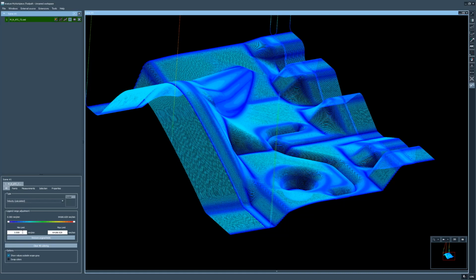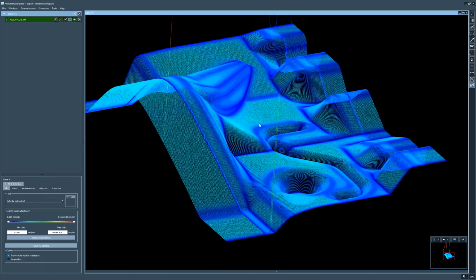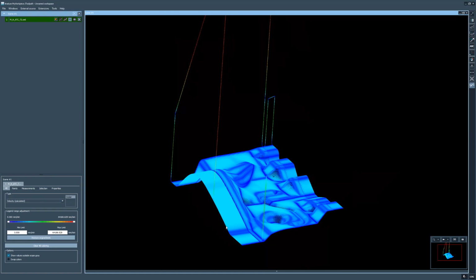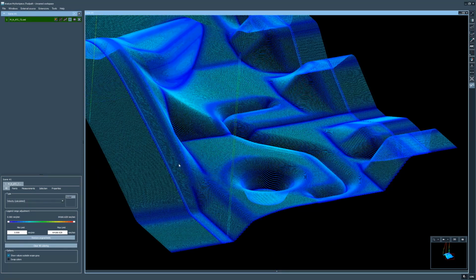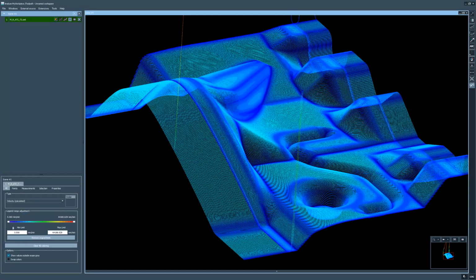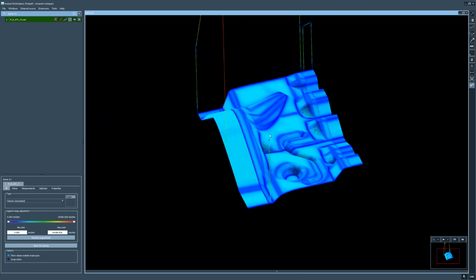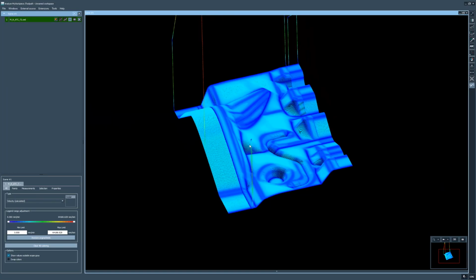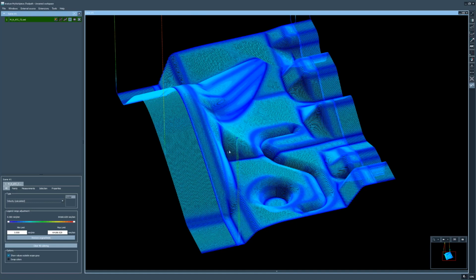Toolpath creates this kind of color coding, and what does it tell us now? It looks very bluish. There are a few red areas, but the rest of it is quite blue. Toolpath analyzes the minimum traveled speed of the tool center point and the maximum. And the maximum goes up to 64,000 millimeters per minute, so 64 meters per minute. And it's quite obvious that these are areas where a G0 code was active, so fast traveling.